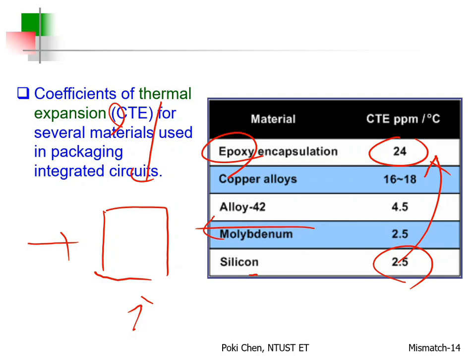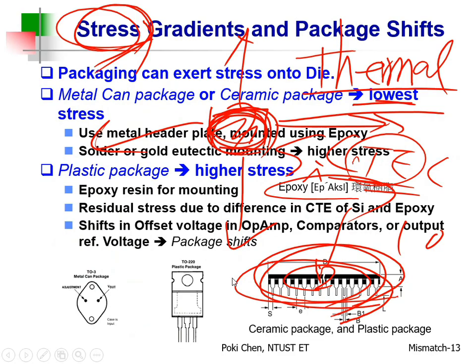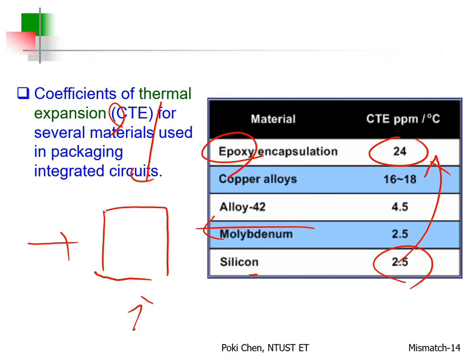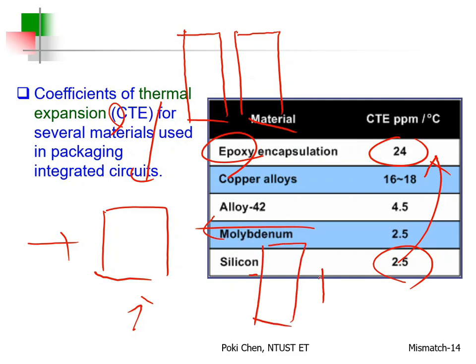So what do you need to do? For critical devices, according to the stress, I don't care it is caused by bonding, packaging, or thermal. I don't care. I would like only to warn you. They need to have the same orientations. For example, one device here, the other device needs to be oriented in the same way. Otherwise, you have one like this, the other one like that. Sorry for that.